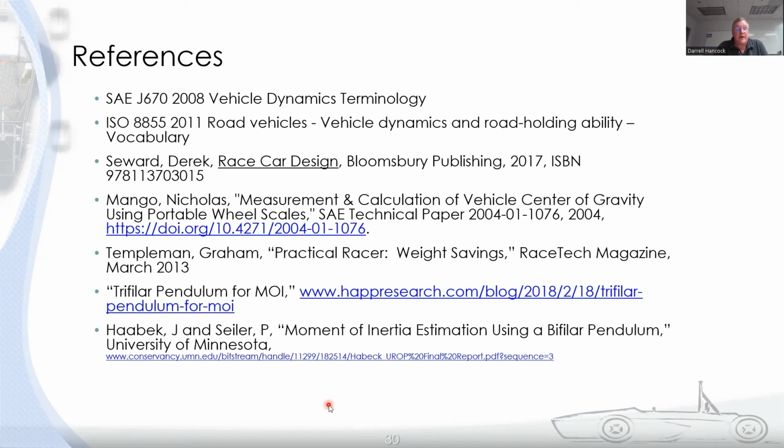And a lot of times they don't have appreciation for the center of gravity height, right? They'll have relatively heavy parts located up high in their vehicle that could readily be located lower in the vehicle, right? So I think my advice would be create that spreadsheet early on, and it will be a living document, right? You'll add parts to it, you'll take parts away from it, you'll change the weights of parts, you'll change the locations of parts, you may change the driver location, right?